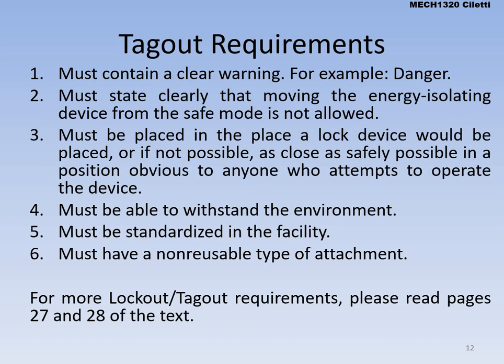You want to make sure that it's obvious so that anyone who tries to operate the device can see that it's tagged out. That tag has to withstand the elements. Generally, they're a heavier duty type of plastic tag or coated paper, so if it's outside and raining, it gets wet and doesn't get destroyed.